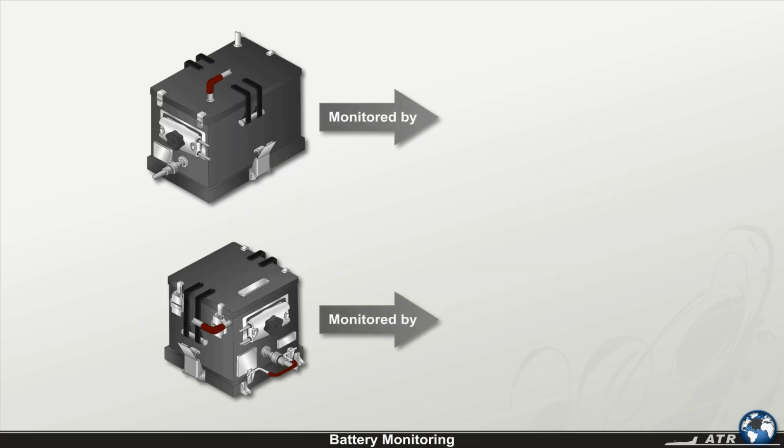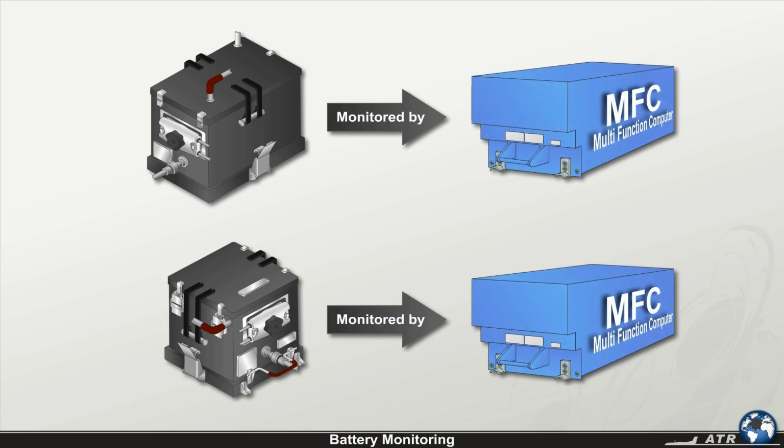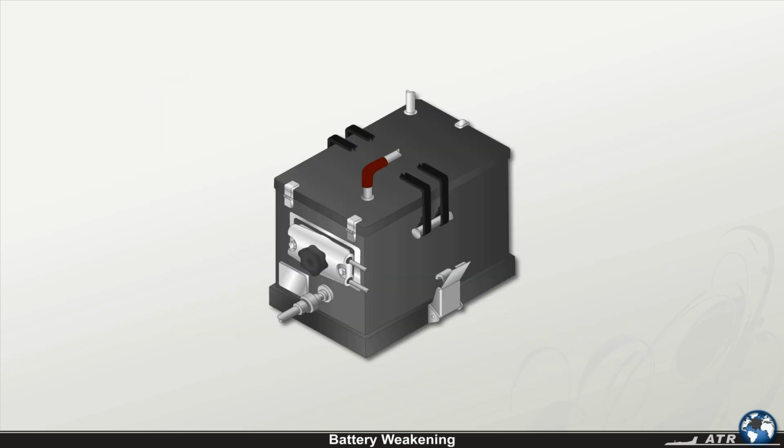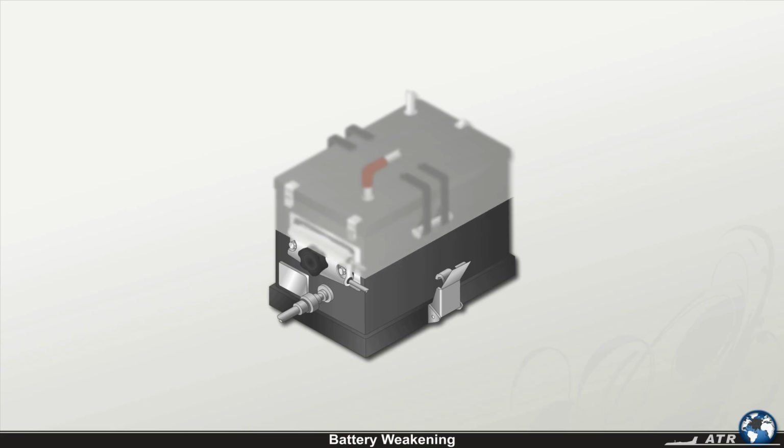The batteries are monitored by the MFC system, which connects the respective battery to the associated DC bus for charging, analyzes the charge current and/or associated DC bus voltage so as to prevent an abnormal battery operating condition or thermal runaway. As is generally valid for batteries, the time of usage of the aircraft batteries on ground should be kept to a minimum to preserve their longevity.